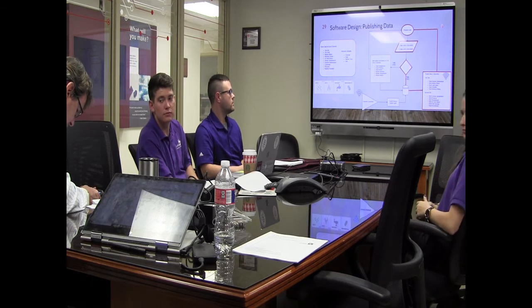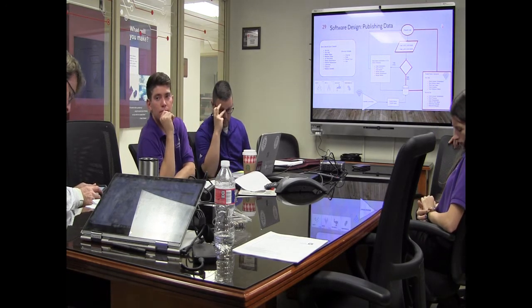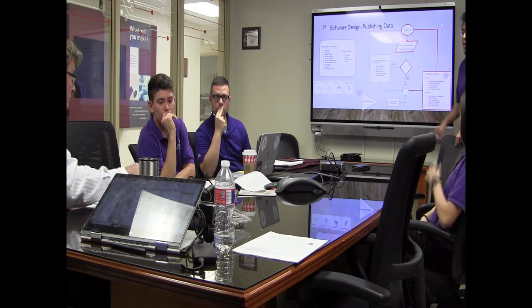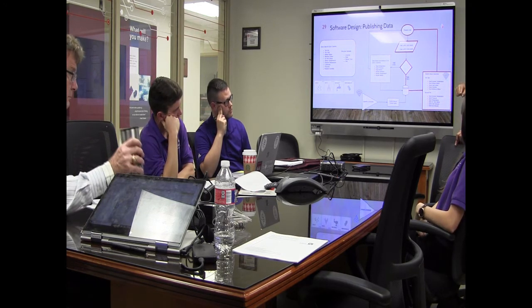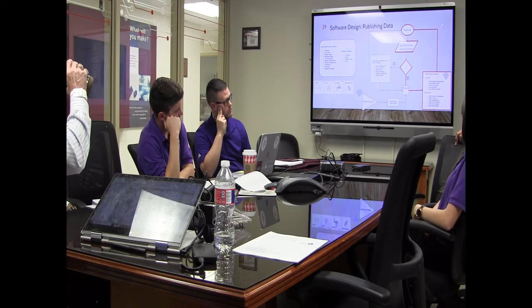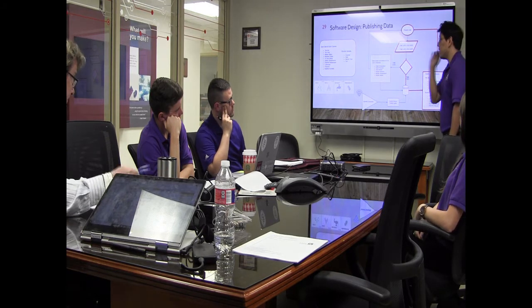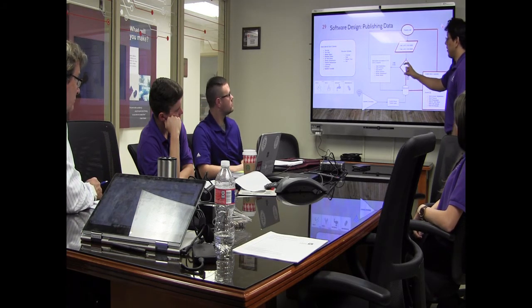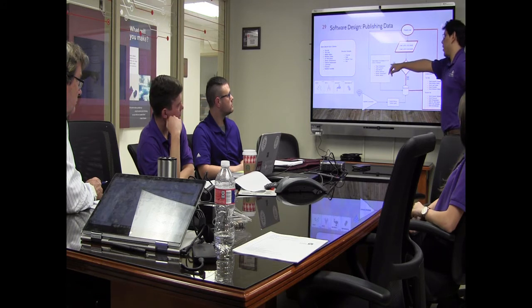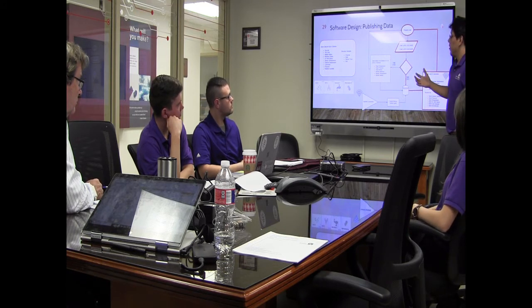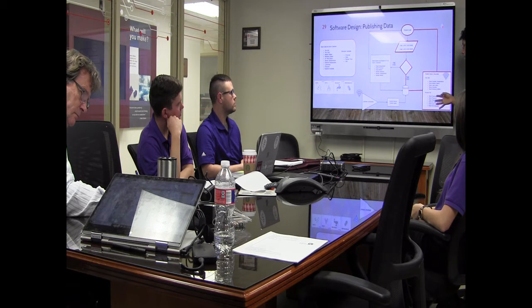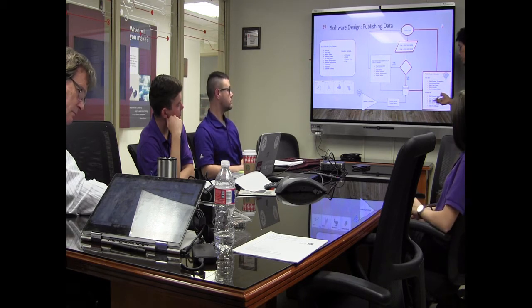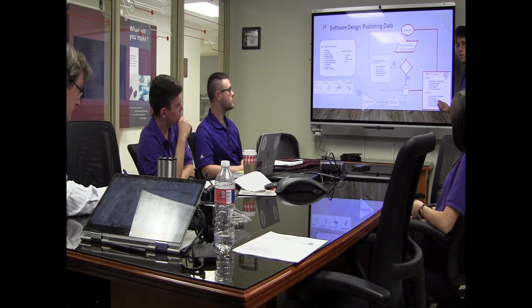Okay, so now let me ask you about the motion sensor. You're getting a digital signal on the motion sensor, is that correct? I didn't double check the setting that it was on, because there are 2 settings: one is continuous trigger and one is kind of pulsing. If it was just pulsing, we were basically seeing it every 2 seconds, so it could have been high or low. But if it was continuous, we would have read it, and it pulses high for 3 seconds. So I feel that if we just reduce the time that we're waiting for each set, and also add the same motion to this next one, it'll be covered as far as that goes.